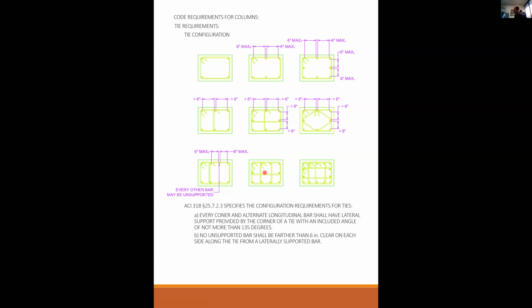Why is it that in all the beams we are looking at, all the rebars are either on the very bottom or the very top? The reason is that gives you the most effective d to give you the most moment capacity. So if you put all the steel in the middle, you have minimal moment capacity. You put all the steel on the perimeter, that gives you the maximum moment capacity. But you can't put it all on just one side, because you can't control if the moments are only being applied in one direction. They can always be applied in both directions on both axes. So that's the real reason.